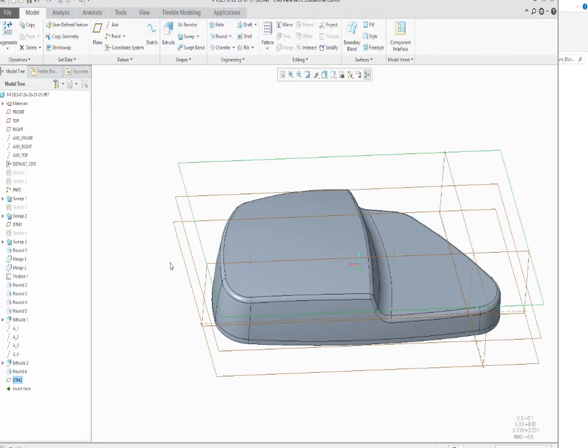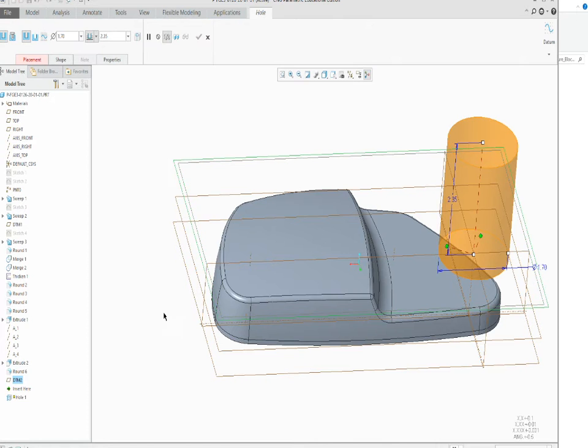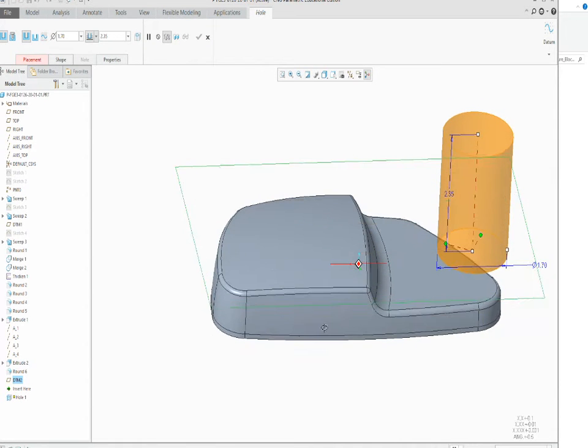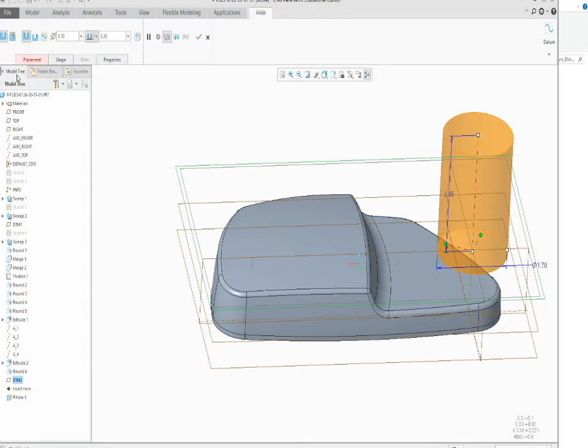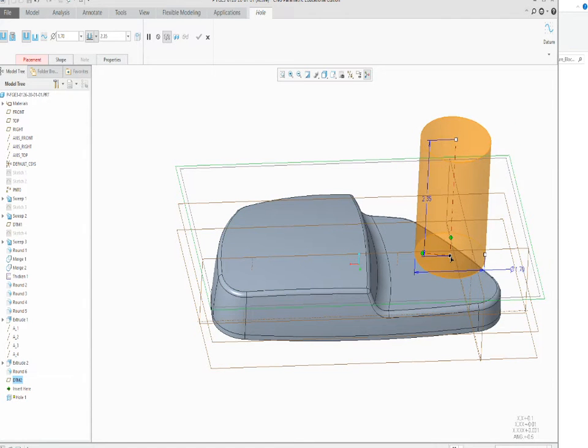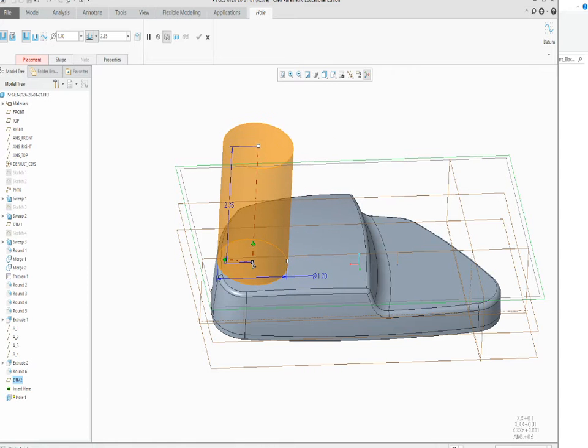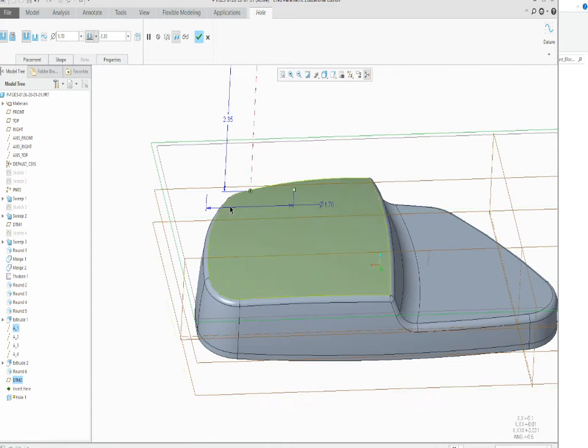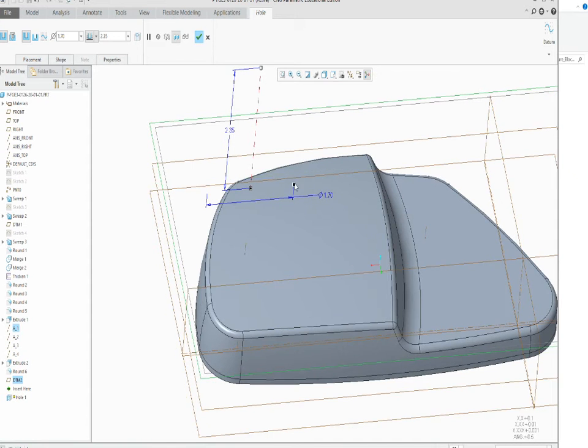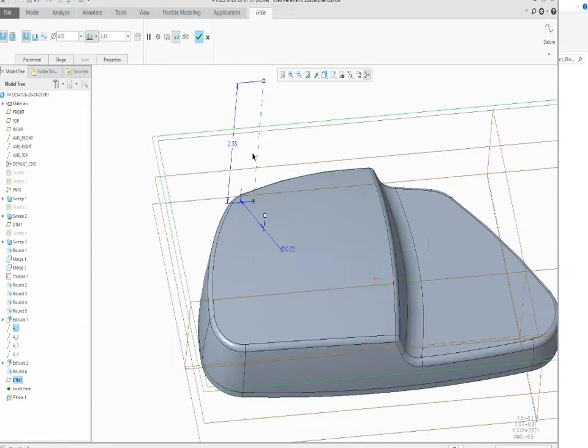Next thing we want to do is call for the hole. When we call for the hole, it might not be going the right direction. So let's first come in and let's project this hole. Grab that little white dot, push down Shift, and then drop it on that axis. Alright, so if you get it in location correctly... mine went over to the far axis.